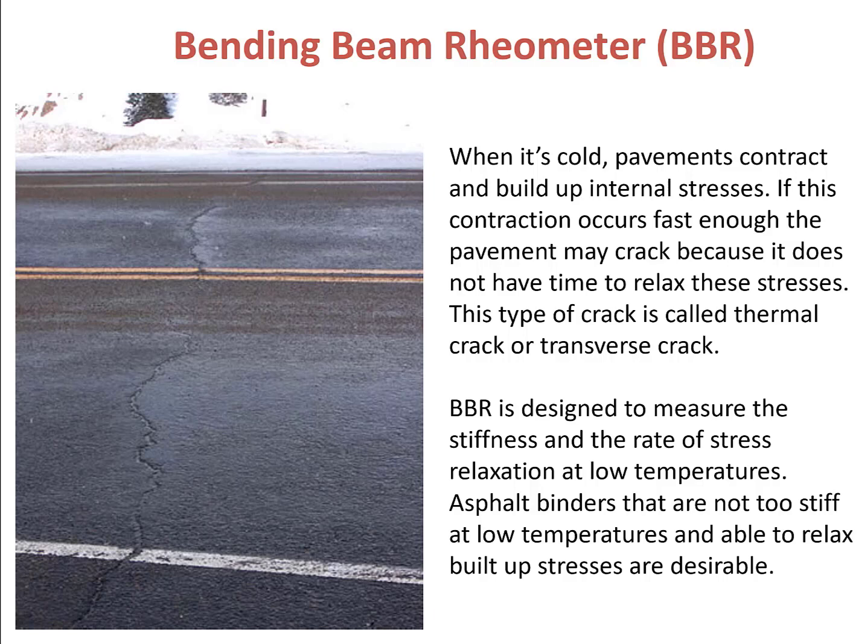Hello everyone, in this video I will talk about the bending beam rheometer test. We often call it the BBR test. When it's cold, pavements contract and build up internal stresses. If this contraction occurs fast enough, the pavement may crack because it doesn't have time to relax these stresses. This type of crack is called thermal crack or transverse crack.